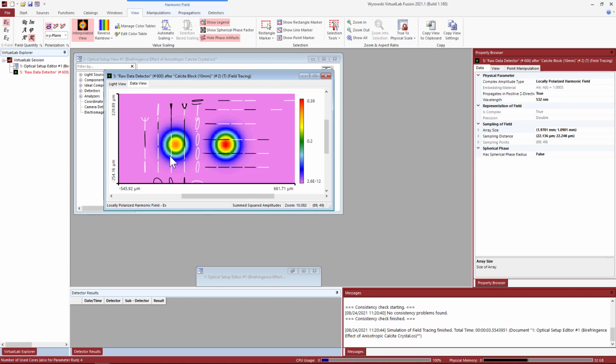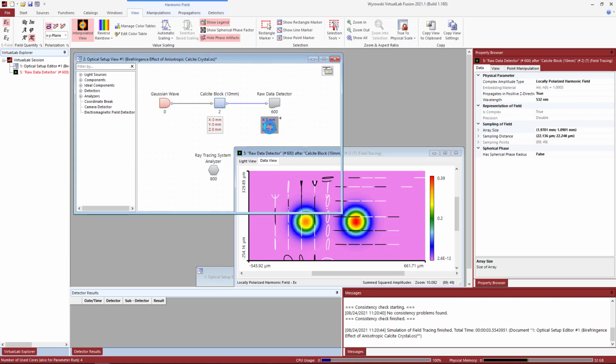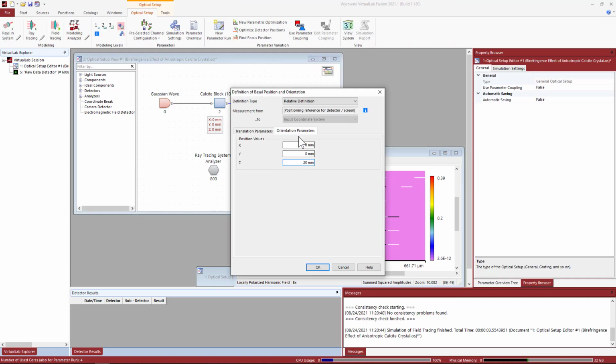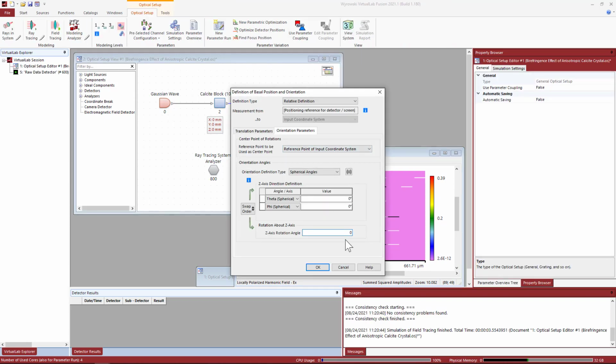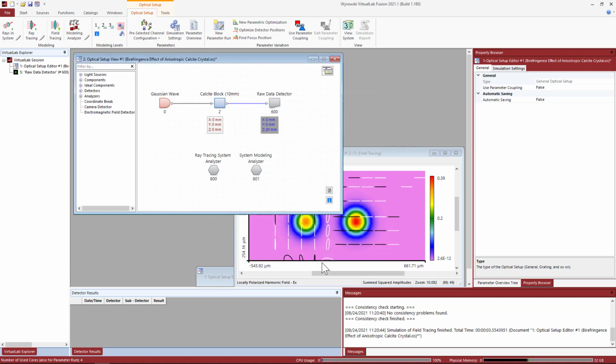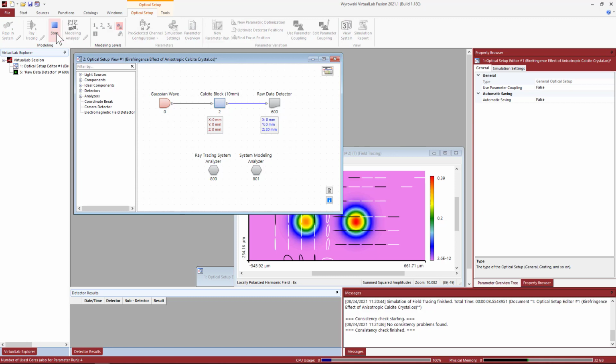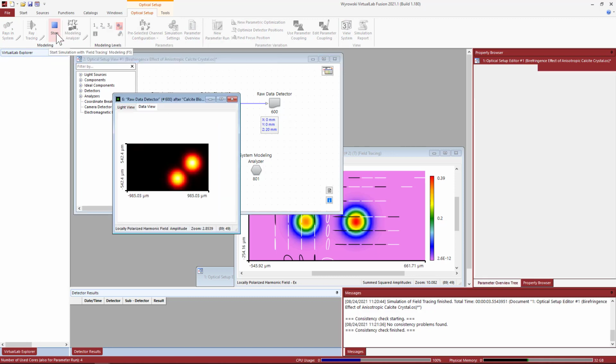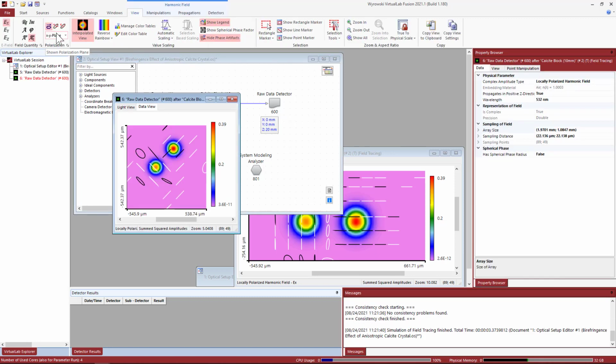Note that we have rotated the detector 45 degrees, and that will influence the definition of a polarization at this plane exclusively. Let me illustrate that by simply removing this 45-degree angle and setting it to 0. That means we, of course, do not use that rotation, and run the simulation again. We're still going to get the same physical result, but now at 45 degrees.